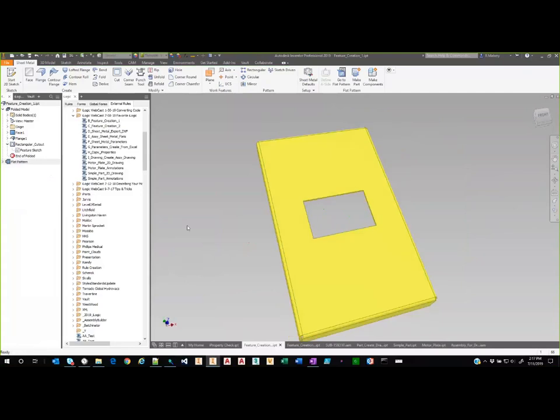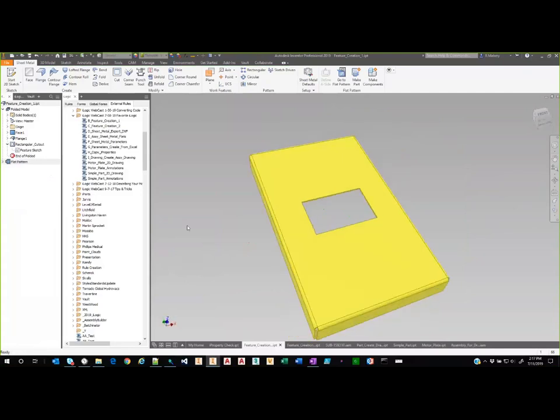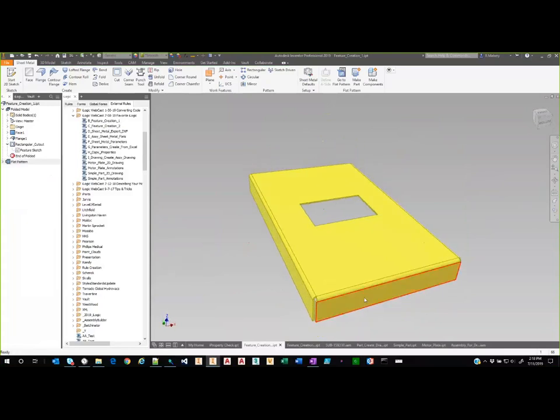Now, attributes have been in Inventor for a long time. Just recently, they allowed us to start creating these on the fly with this assign name function. Okay? That is really creating an attribute. It just calls it a little bit different. It makes it more user-friendly. But I can do the same thing with something like this. I can assign a name to that entity and then therefore find that entity later on when I want to do something with the code. Okay, I'll go ahead and cancel out of that thing there.